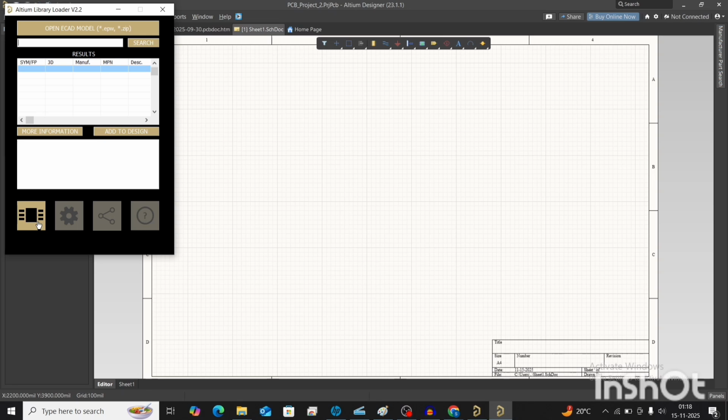What you can do is find a part number of a component from a reputable manufacturer whose footprint and all other specification like say pin mapping or mechanical dimensions, everything matches with the component that you originally wanted to use.